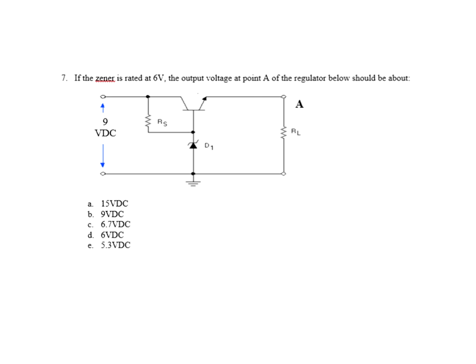Oh, not another one of these, McNeil. Well, yeah, because I don't want you to miss them. You might see 3 of them on that test. So let's get this one right this time. What is the output voltage from this? The Zener is rated at 6. The voltage drop on the base to the emitter is 0.7. And therefore, I'm going to lose 0.7 from the base to the emitter. My regulated output voltage at point A would have to be 5.3. Would I put 2 of these on your practice quiz if you weren't going to see them? No, I would not.